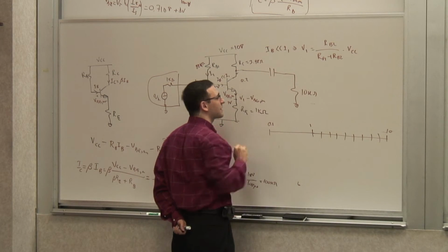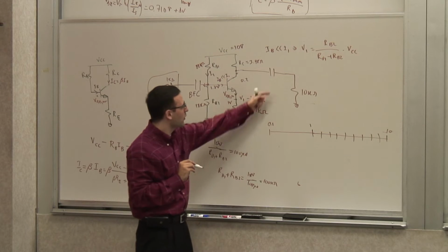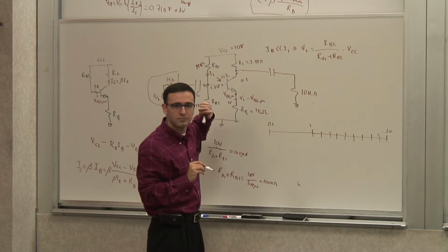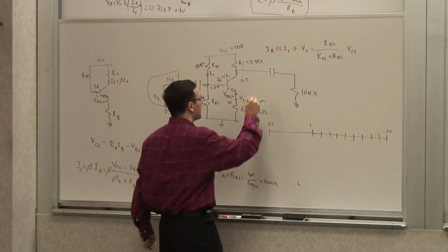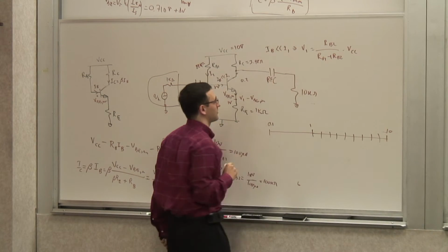For now, I need another capacitor here, right? Because again, I don't want to short this to ground and mess up my output. So if I were to design a discrete circuit like this, I need another big fat capacitor.